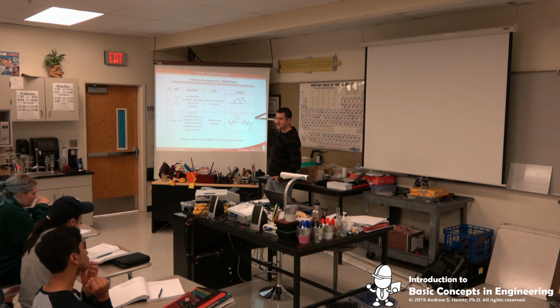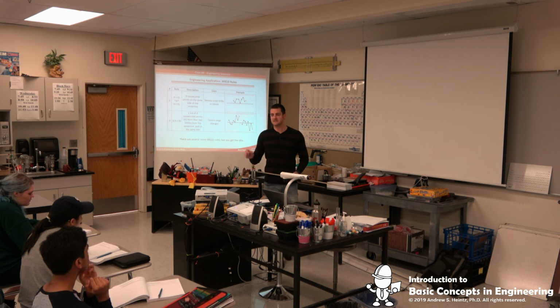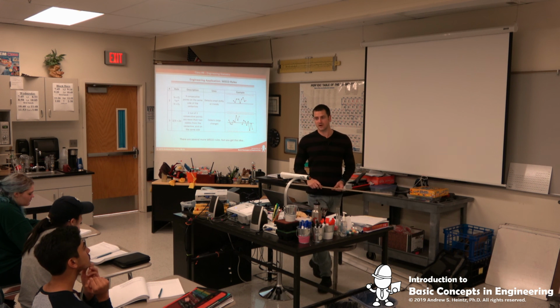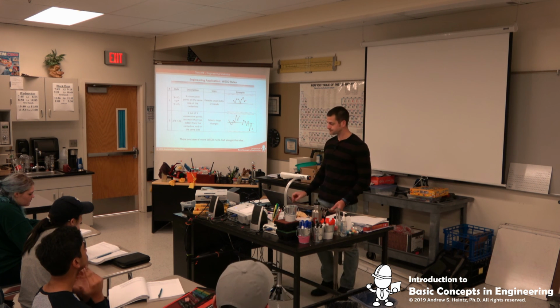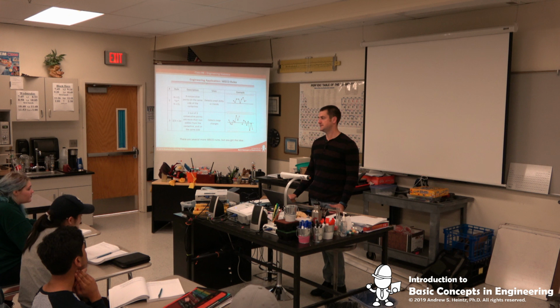So the gray line is not out of control. The gray line is your 2 sigma. So if we ever get 2 points out of 3 that are outside that, that's statistically less than 1%. So again, we flag the process and we can bring it down and investigate. Okay, any questions on that?